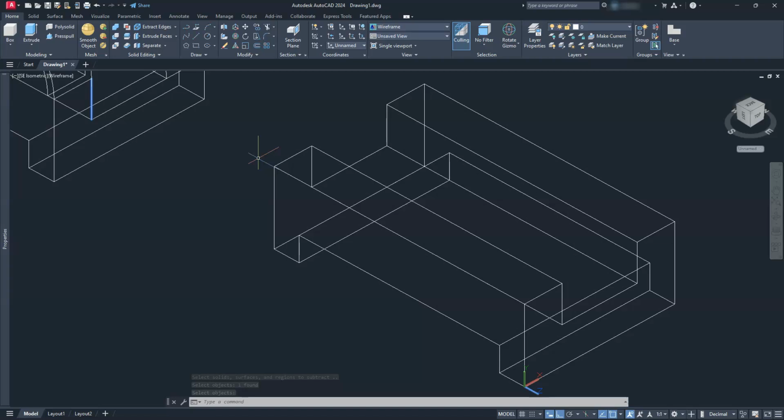Next I need to go ahead and put these little humps on here, or arcs, or whatever you want to call them. Now, depending on how you want to manipulate this, you can put it in one or two places. I can go ahead and specify my UCS somewhere here, and then I can use just a negative 25 to go to the left, make my circle, and away I go. Let's go ahead and try it that way. Or, you know what, now that I'm thinking about something, there's another command that I do want to show you that we haven't had too many chances of using, and that's going to be the slice command. So what I'm going to do is create two cylinders, and then subtract one of them out of it, and then slice it, and then we can go from there and copy it. And I'm just now thinking of this on the fly.